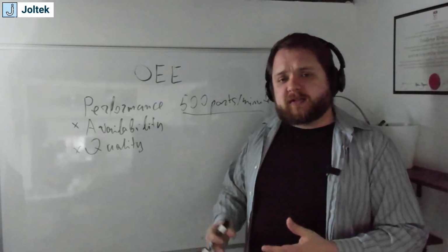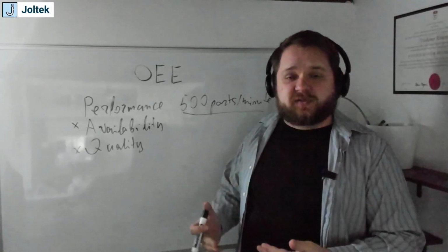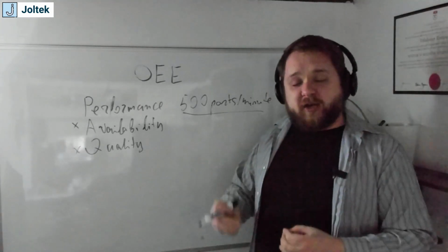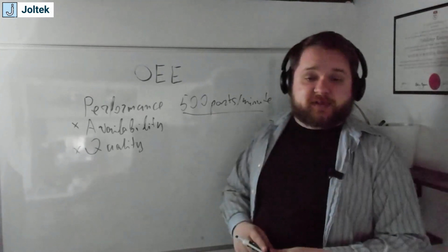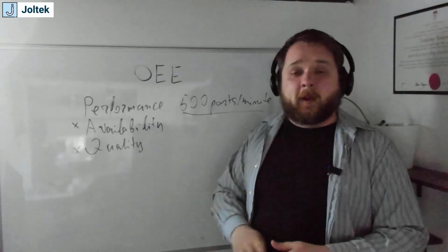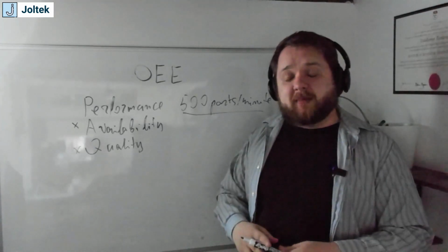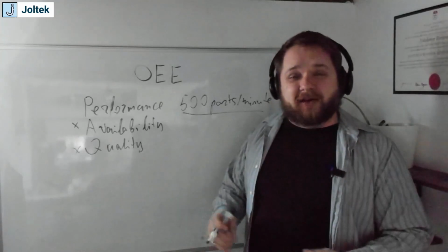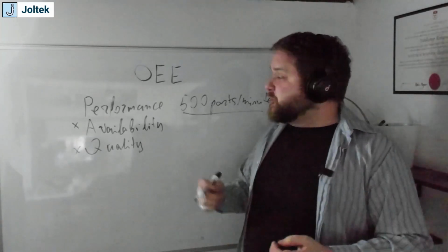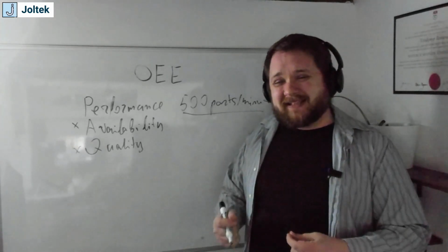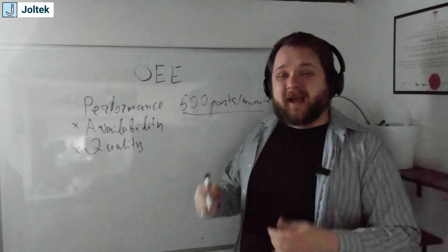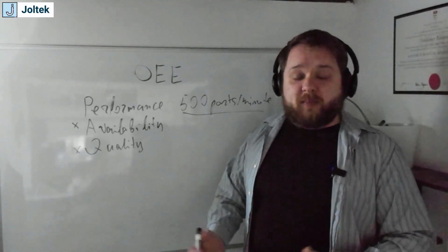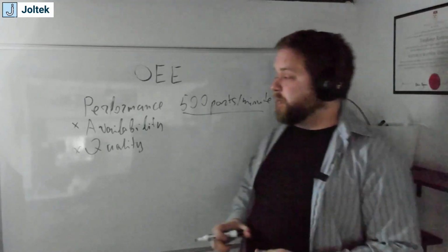I've also seen processes where there are variations depending on some of the other set points. So it's possible that the target rate for the machine is specified here, 500 parts per minute, but over a period of time, that machine never truly runs at 500. It usually runs a little bit below, so 450, 480. Your tool or your MES system should be able to calculate performance based on that exact speed. How granular it needs to be depends on your equipment, and of course, we can get into those details a little bit later.